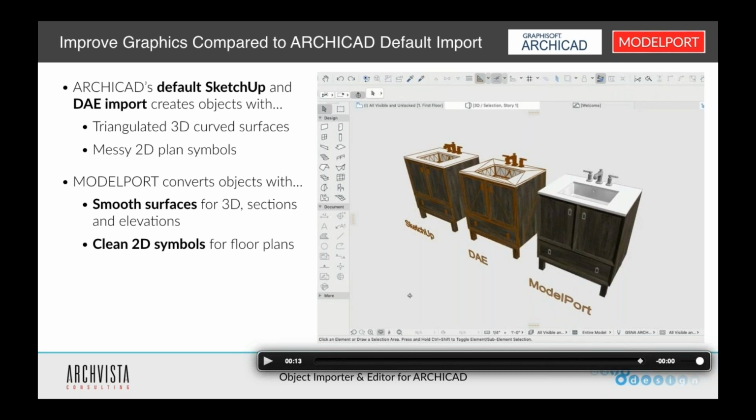And a lot of that line work, yes, we could go to our visualization, go to 3D styles, and turn off the line work there using the contours option in the 3D style settings. You can turn contours on or off. The disadvantage of turning it off is that it also turns the contours off for other elements where you might want to see those contours. So you're basically eliminating something for the purpose of a problem you have with the object.